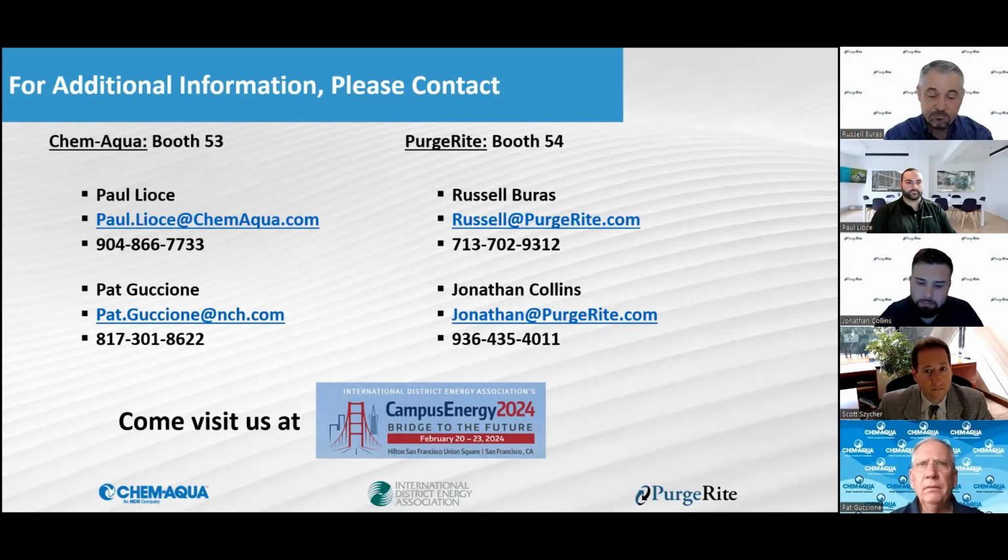So we have found that the best industry practice that we can find out there has been 5 to 7 feet per second. And we've done some testing, and we're in the process over the next year and a half of doing some more data points and testing to validate some of these velocities. So that's basically how we look at it. We feel like we can remove most debris doing that.